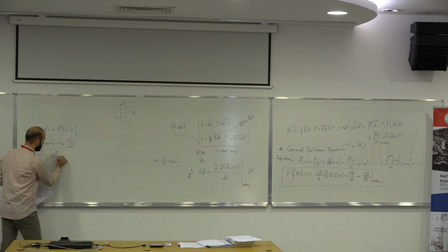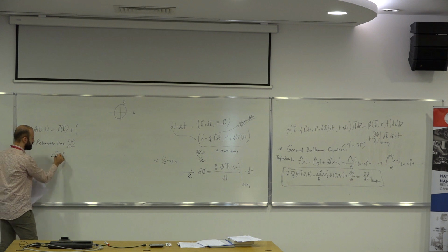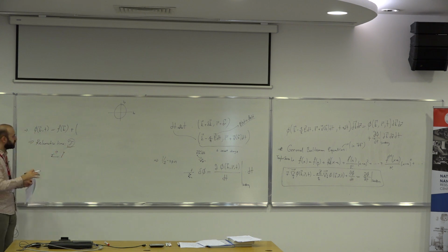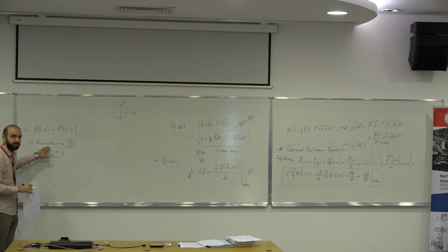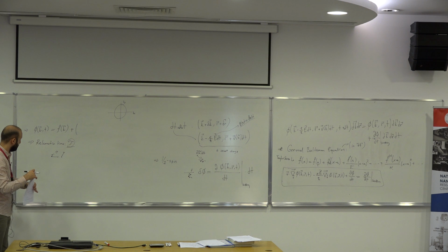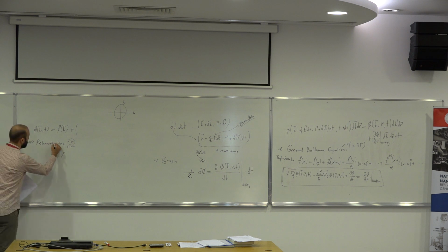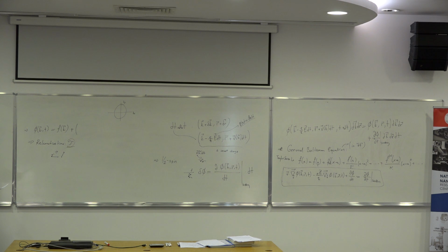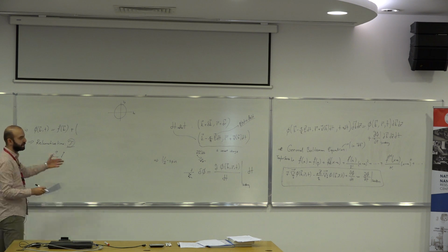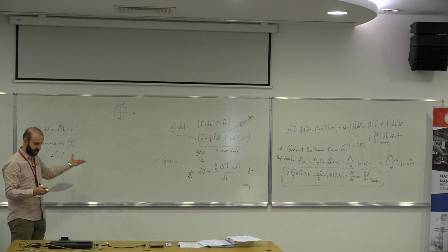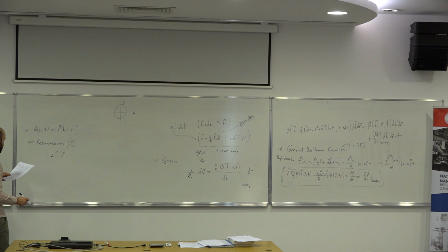So once it scatters from a scattering center, it will have tau time to follow the electric field. So the relaxation time defines basically the time that it travels without any scattering event. So it's the tau that we defined in our Drude model. It's the same quantity, if you like.